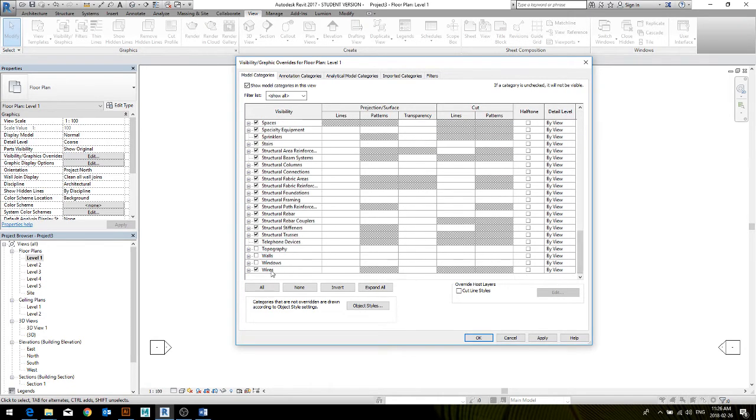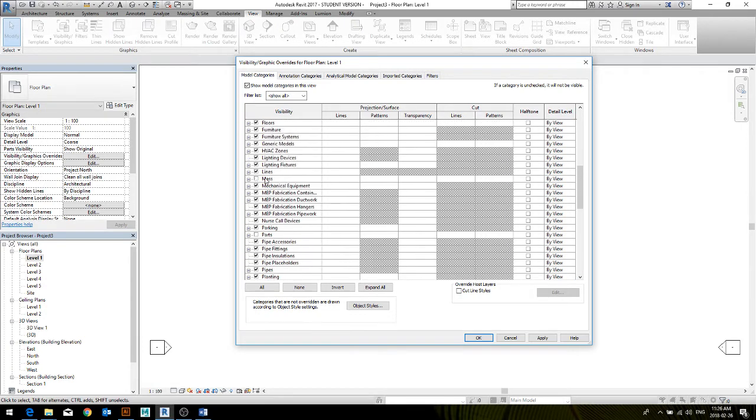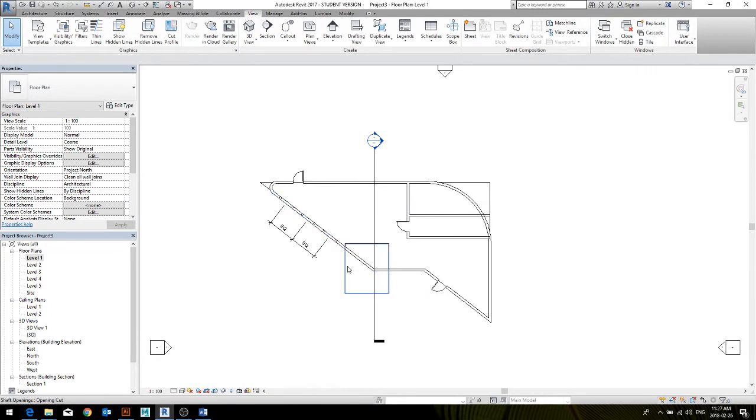One thing that is mainly an issue and you will use a lot is to turn on and off your massing, because by default the mass is to be turned off. So if you have a mass imported from Revit, from Rhino or something else into your file and it's not showing up, it's because probably your visibility graphic mass is turned off. So you need to go back, turn this on, say okay, then your mass will show up if that's the reason why you're not seeing it.